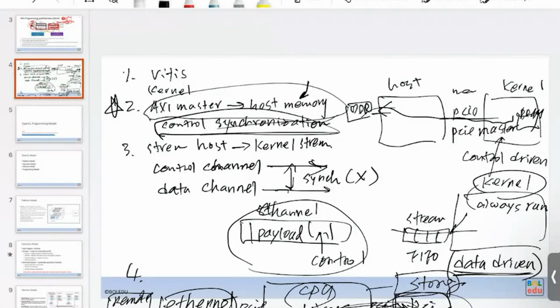Yeah. And today's inside the chipset, there is a PCIe switch. Today's chipsets, okay. Before, like over 10 years ago, Intel chipset doesn't support that, but later they have a chipset supporting PCIe peer-to-peer transfer, so that they can forward a PCIe packet directly to another PCIe bus. Yeah, so you can do things like that.